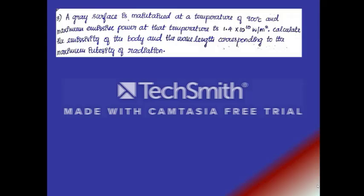This is the third problem we are trying to solve. The problem says a gray surface is maintained at a temperature of 900 degrees Celsius and the maximum emissive power at that temperature is 1.4 x 10^10 watts per meter square. Calculate the emissivity of the body and the wavelength corresponding to the maximum intensity of radiation.